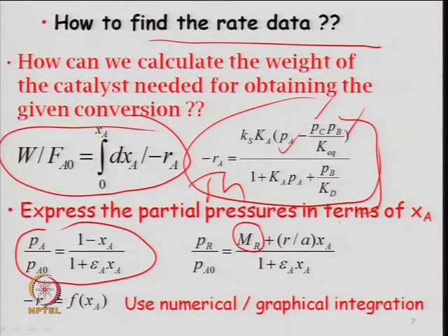So, you know that A plus B gives you C plus D. One can very easily write down the stoichiometric ratio based on that limiting component. So, this is written based on that, because A moles of capital A are reacting and forming R moles of the product. So, per mole of that A, how many moles of R form, that is what is written here, and you just make a simple stoichiometric table and balance it.